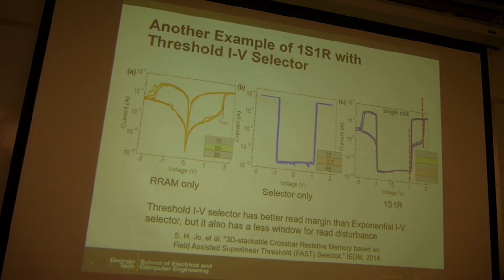This is really ideal, because here, at write voltage, you will get tens of microamps. And then at V/2 here, you reduce the current to the picoamp range. So this is really good in terms of the nonlinearity, the definition, the current difference between those 2 points.